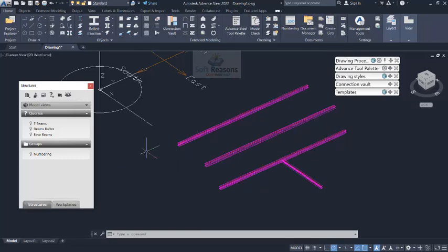If you want to query these beams now, those beams that you have drawn with respect to first floors, you can just select it right here and then click on execute. Now you execute, and you can see it's been selected successfully. You see all of these beams have not been selected. I've been using row I sections, but due to that separation using query, you cannot have them selected together. So this is how you query. For instance, if I pick this now and right click, I click execute query, you see this has changed.